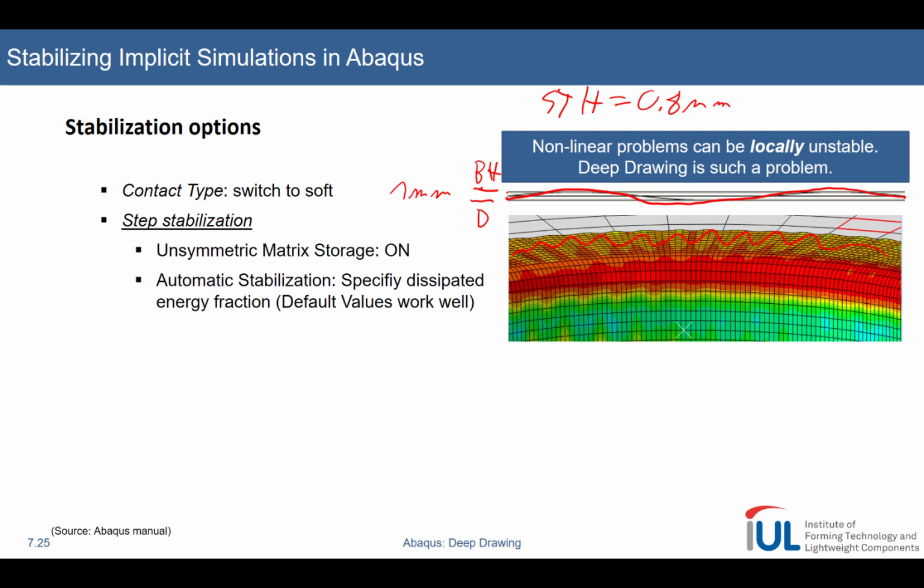And where does it come from? Remember that the way your deep drawing works is that from the left and the right, in circumferential direction in your flange, the material is pushed together. And if you have some space for the material to go, so the 0.1 millimeter above and below the sheet, then you will actually see such a waviness emerging.